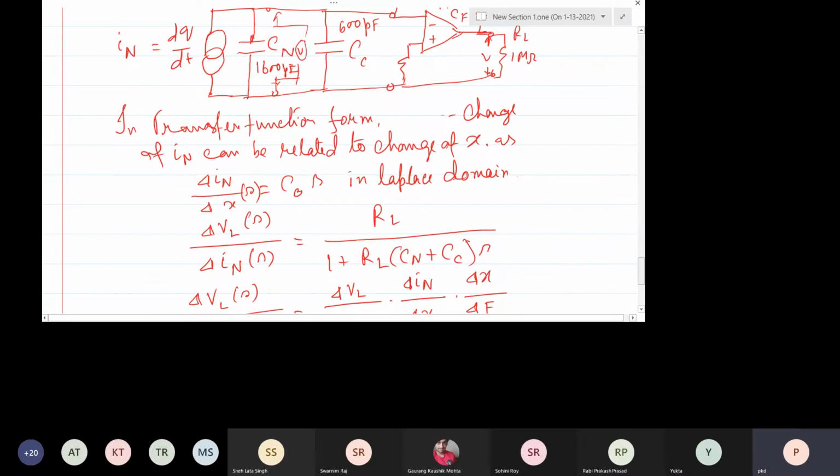In fact, if we have a very high input impedance, like 10 to the power 13 or 14 ohms, such input impedance voltmeters are available. Those are called electrostatic voltmeters. If we use those here and measure the step response of a piezoelectric crystal, it will not die down. That has been shown experimentally. It basically stays there. If you give a static force, there will be a charge difference which will be maintained.